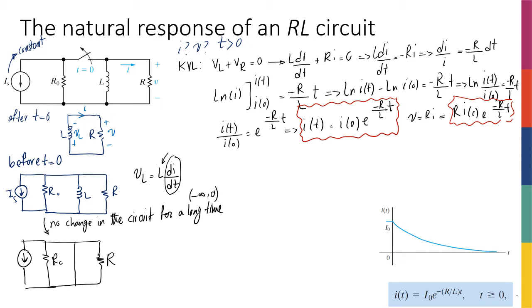There's not going to be any voltage across this, so it's going to be similar to an ideal wire which doesn't have any voltage across it, right? Okay, my circuit just got very interesting, because now I know that I have a short circuit that is in parallel with two resistors. Now I don't care what the value of these resistors is.